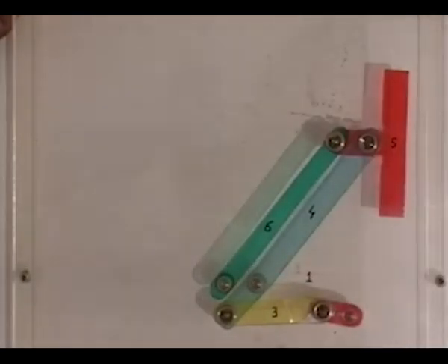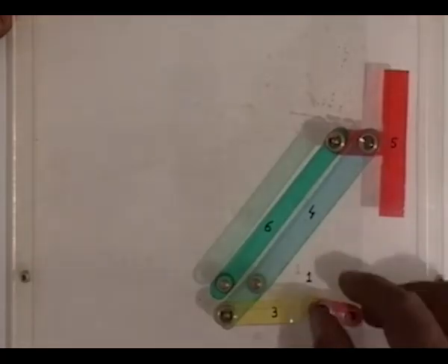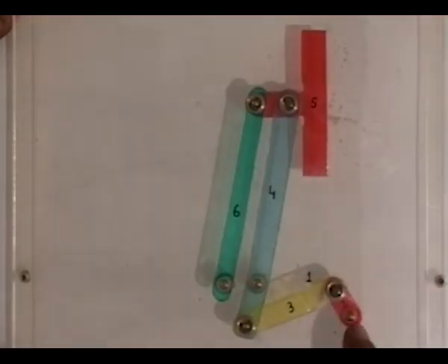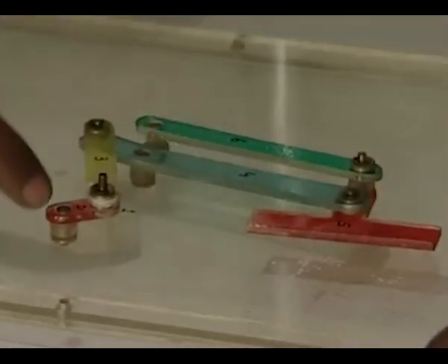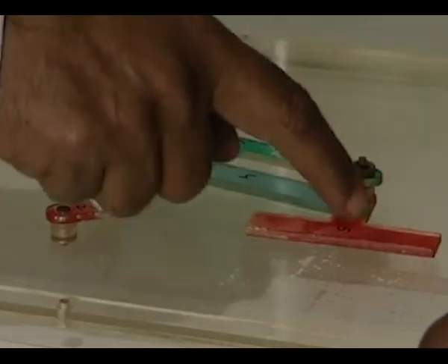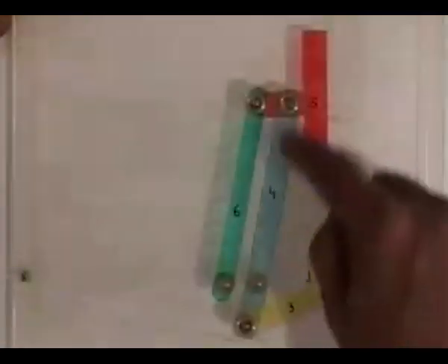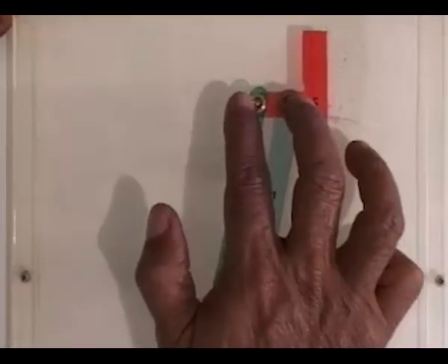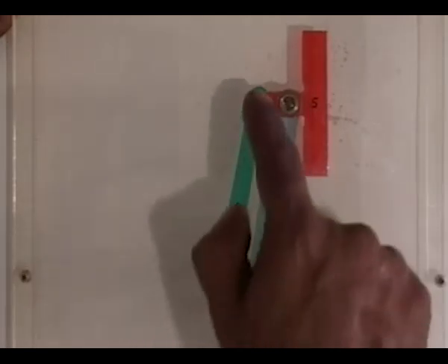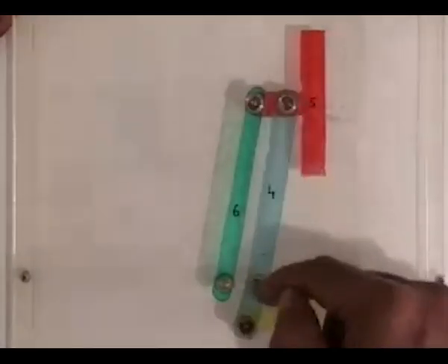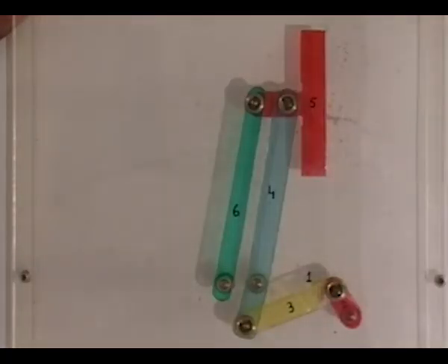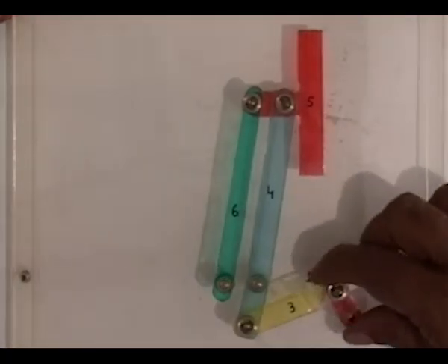We demonstrate the same wiper mechanism that we have just now studied. This is the same wiper mechanism consisting of a crank rocker consisting of link 2, link 3 and link 4. O2 and O4 are the two fixed hinges. And there is another parallelogram linkage starting from here, link 4, link 5 and link 6. This link length is the same as this link length and this link length is the same as this link length. So, it is a parallelogram, and we should note, because it is a parallelogram linkage, the coupler remains always parallel to itself, it never changes its orientation.